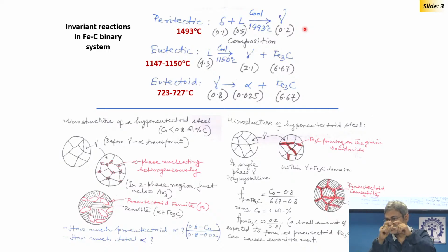So, you can extend the austenite domain, so you can avoid delta ferrite and go directly into austenite; that is what people try. Otherwise, you have to do some heat treatment to get rid of it, because it can be prone to cracking. That is a problem that happens.